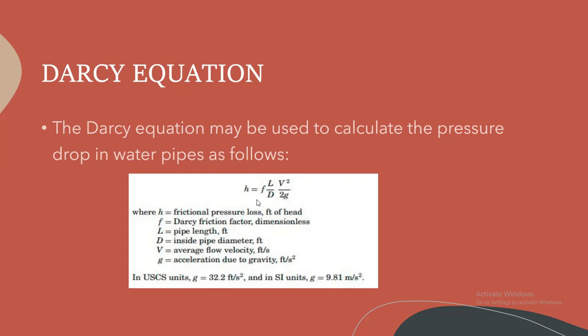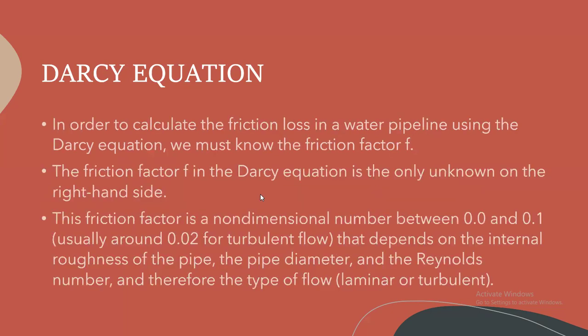So the only thing which you don't know is this F. The friction factor F in the Darcy equation is the only unknown on the right-hand side.